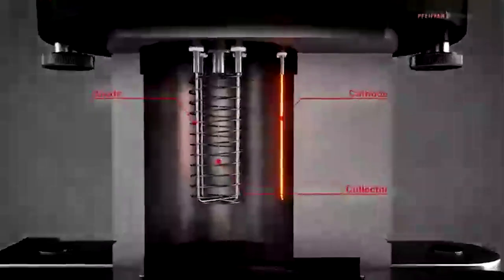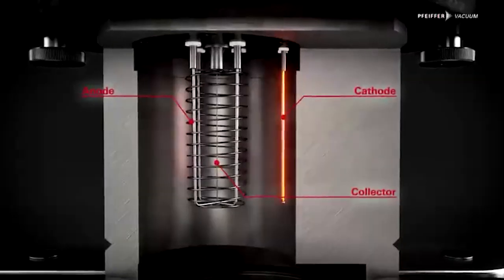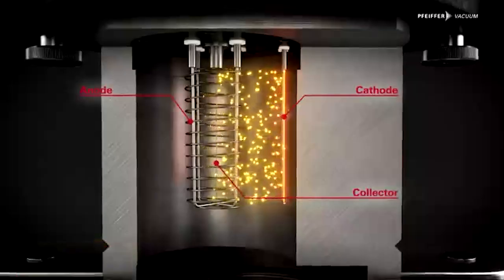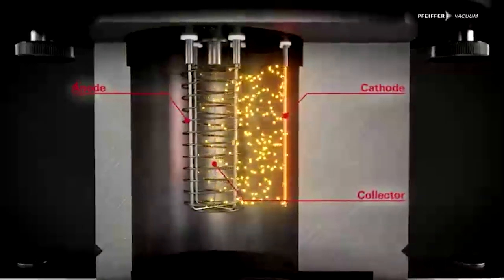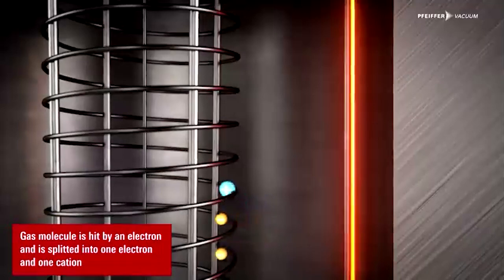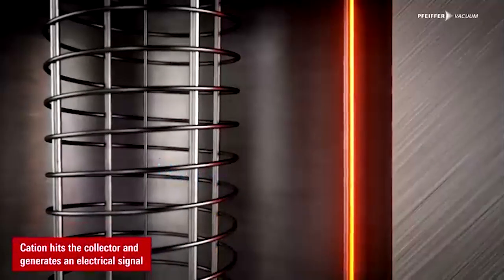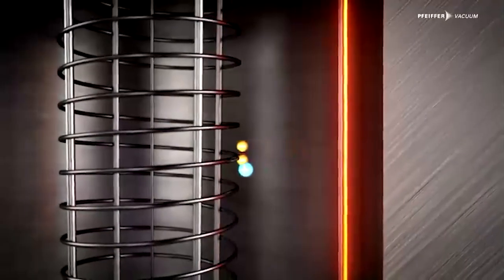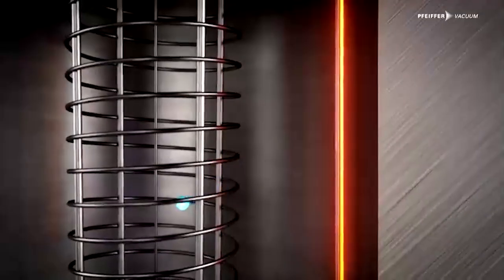This is a nice video. So we'll play this 10 times? No. All right, so here, and thank Roberto for finding these. So here's the cathode. Heat up a filament, you get a lot of electrons off. Electrons are attracted to the grid. The ionized particle comes here, and we get a reading. If there are more gas molecules, then this current is higher.